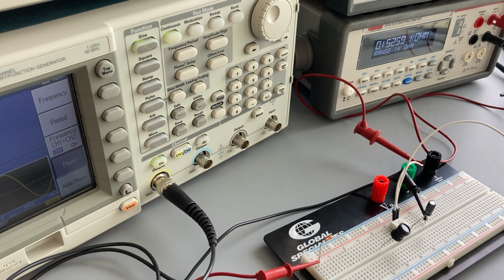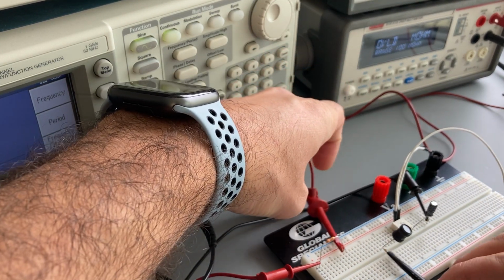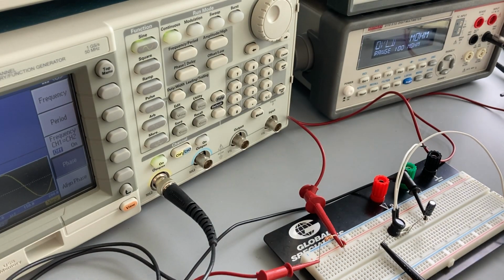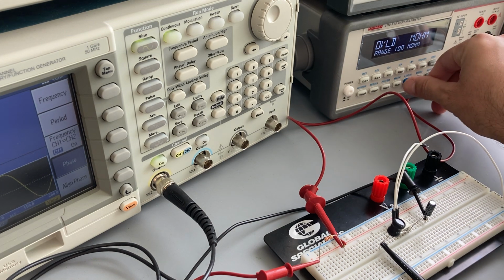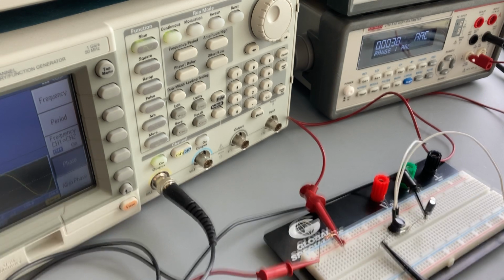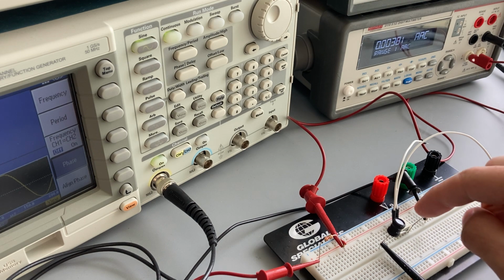And I already have the formulas all worked out so that I just have to punch in the values and it calculates the power at that resistance. And then I switch my inputs here, go to a current measurement, and this is giving me the RMS current. Punch that into Excel as well. And then I see that gradual reduction. So I'm switching between a current measurement and a resistance measurement for this R load.